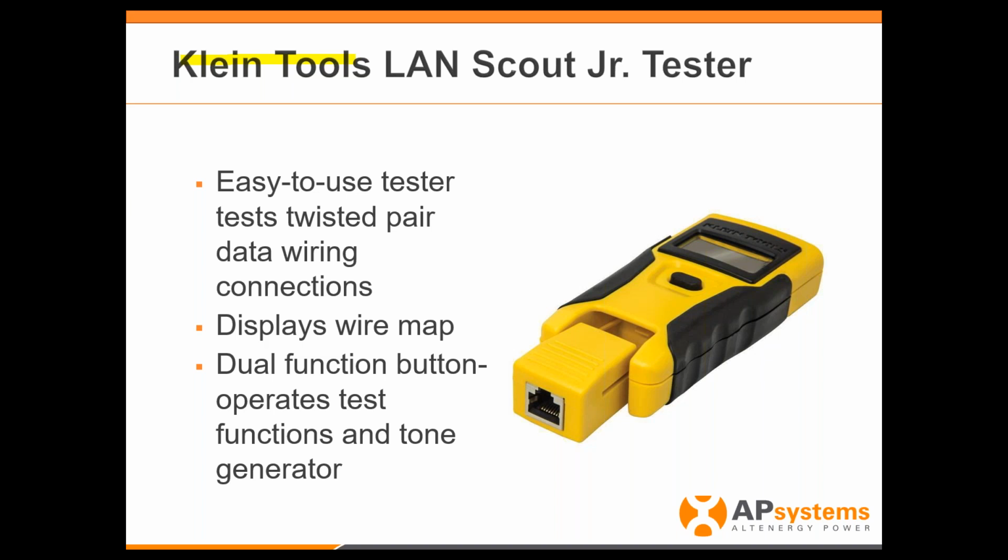So this tool right here is nice because you're actually able to test the wires that you're using. Because if you think you got a bad cable, you can test it with this. You can actually test the cable. You can actually do the wire map and make sure the wiring is correct if you made your own cables. And you can also use it as a toner as well. So let's say there is wiring in the house. You're trying to find where the other end of the wire is. That's where you use the toner as well. So it saves you a ton of time by doing the job right.